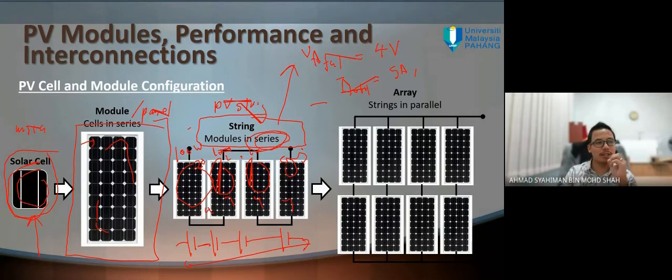Why do we want high voltage? Usually we use an inverter, so it becomes the input to the inverter, a grid inverter. At a solar farm, for example, recently they are looking for the highest voltage, not the higher current, because the channel has the highest voltage but still gets the power. It has an MPPT function so that the extra voltage will be converted to extra current, extra power. It will track for the highest.